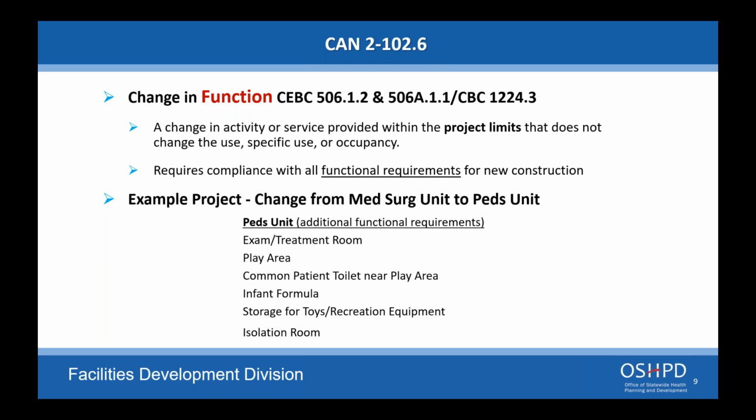Richard, is a re-roofing project considered a project or just cosmetic? Re-roofing is a project. There are expedited permits for small ones, I think under 400 square feet, like patching a roof, but a re-roof project would be considered a project. We're actually going to be submitting an expedited permit package for re-roofing for skilled nursing facilities, but a lot of the tips in there can be used to apply to regular projects. But yes, re-roofing is a project because there's other things to be looked at rather than just the material going down.